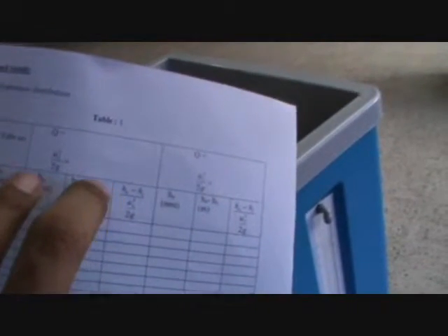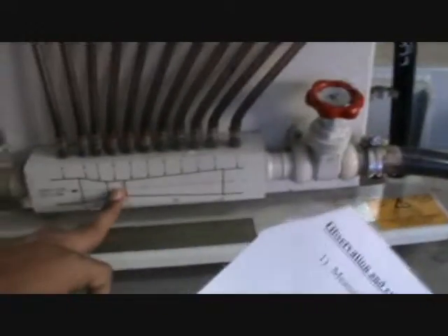You know Hn, and you know H1, the height of water column at section number 1. So you will get the difference Hn minus H1. Then in this formula U2 is unknown. U2 is the velocity at cross section 2, that is the throat section, section D. So how do we calculate this velocity?